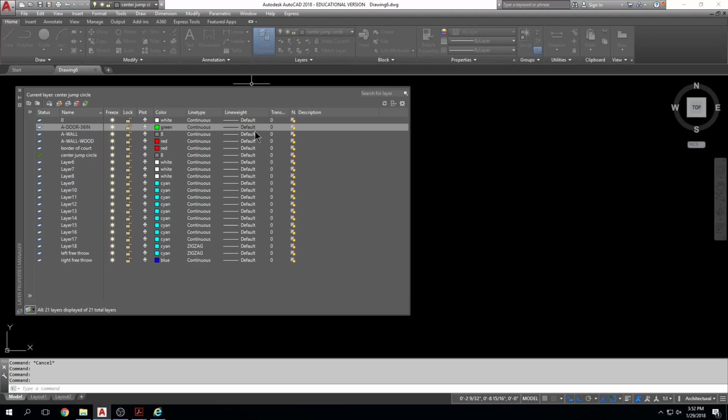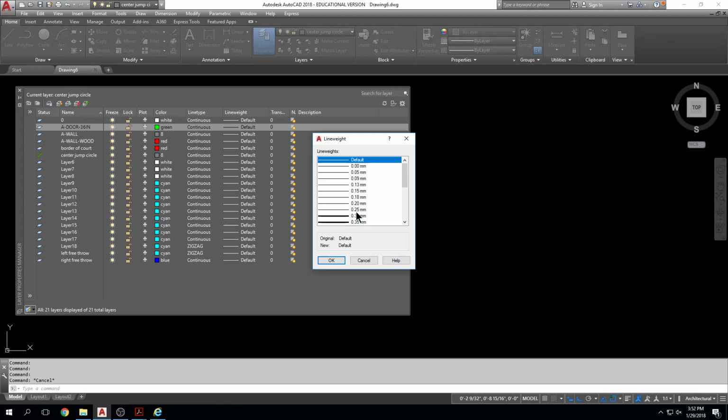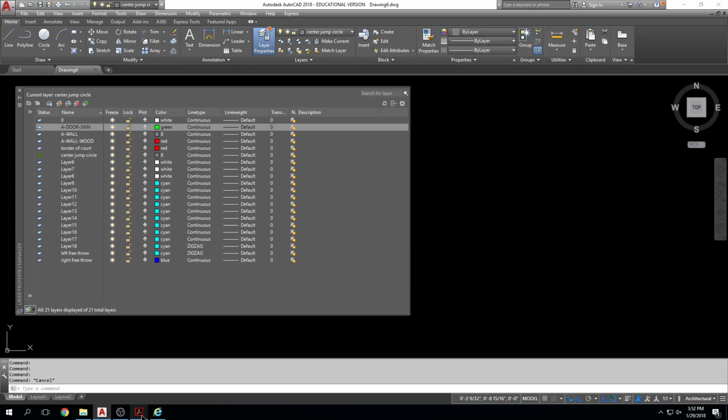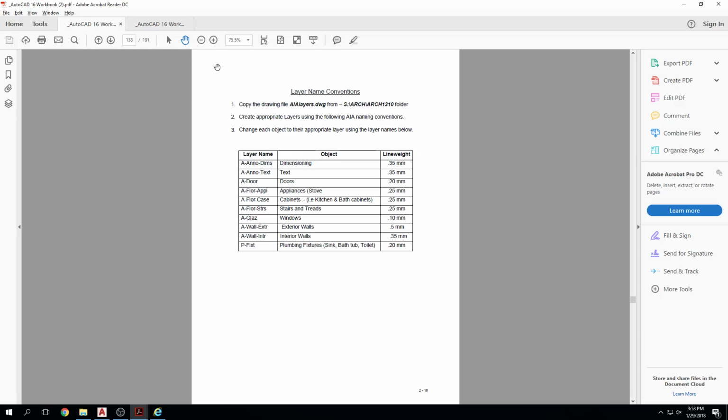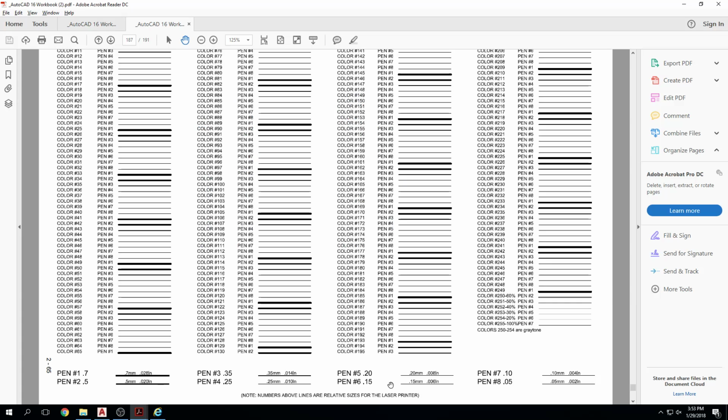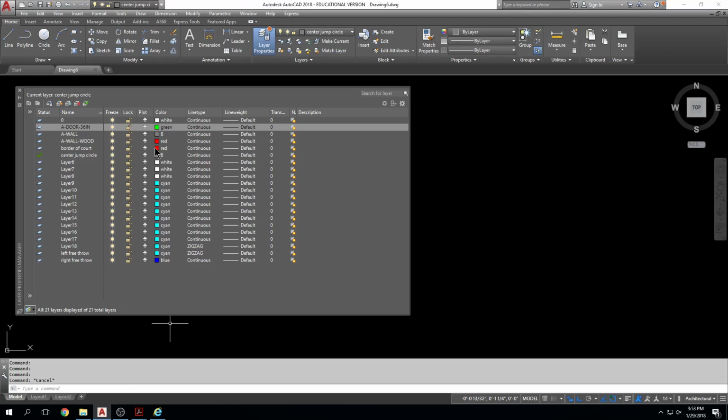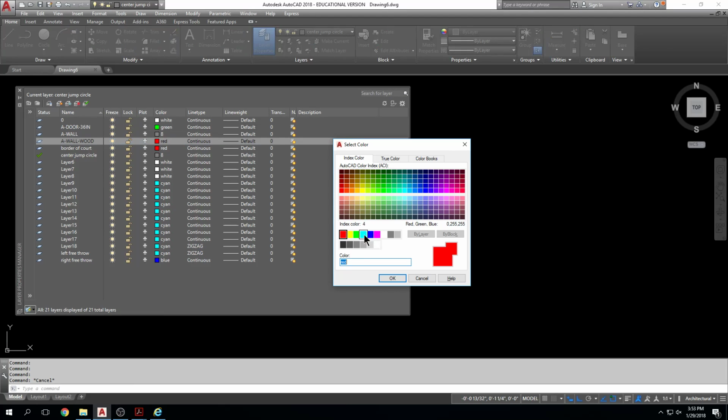This is where I said, you say 0.35 millimeters, you're looking for 0.35 millimeters, and most beginning students find it right here. But then you remember, wait, she said don't change that, but I don't see 0.35 millimeters anywhere, right? So I just wanted to clarify that in this booklet, it says create this layer on 0.2. Okay, well, 0.2 is pen number 5. Right? And when I go to AutoCAD, pen number 5 is blue. Okay? So that's what you're going to be doing with those.